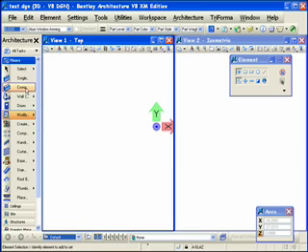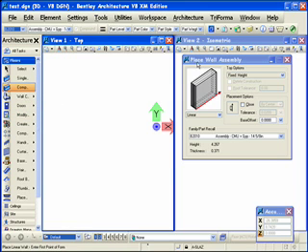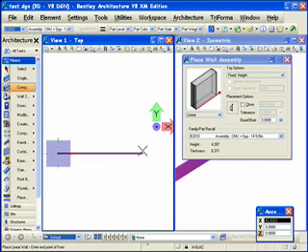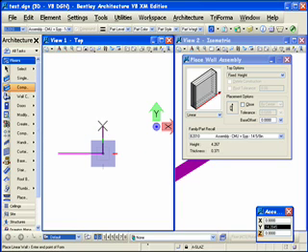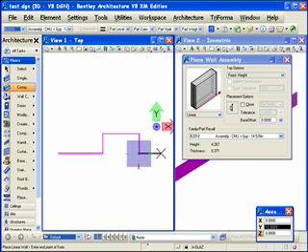In this case I'm going to be using the compound wall manager here and the place wall assembly. I've chosen a CMU with gypsum board here. I'm just going to place a run of wall, let's say 25 feet, and you can see Architectural is helping me out here. I'm going vertical here and I want it 10, and then we'll do another, I don't know, 20 feet, and we'll return it back to 10 here. You'll see there that Architectural is helping us, and we'll just run it along there 15 feet.